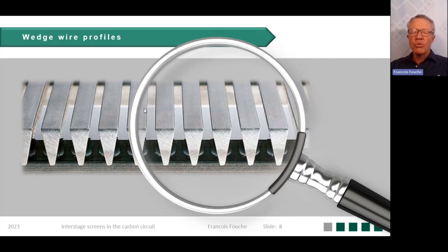These cylinders are supplied almost exclusively with wedge wire as screen media. And looking at my slide, you can see why if you look at the wedge profile of the wedge wire. You're also able to see why wedge wire makes for an ideal screen media for these cylinders if you consider the aperture relief that you see on screen. And this is essential to prevent pegging of these cylinders with near-size carbon and with grit.